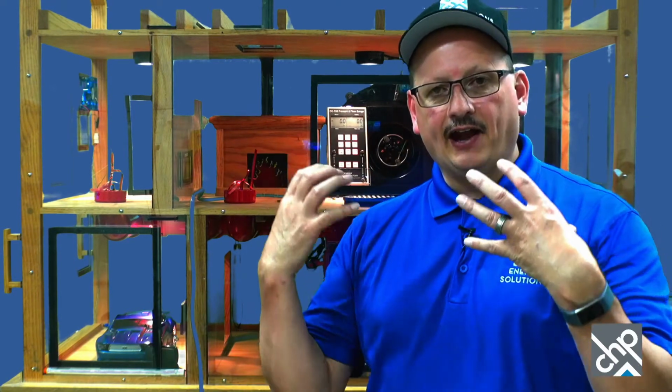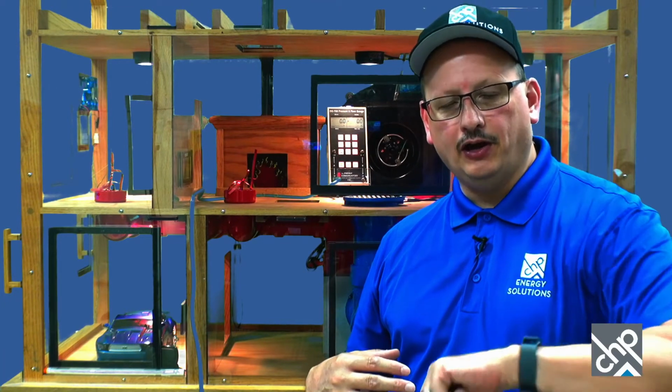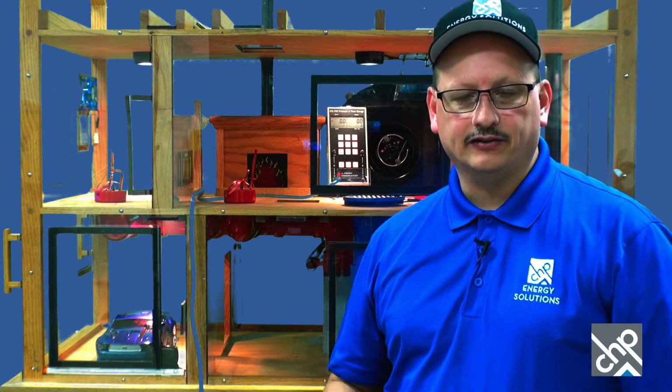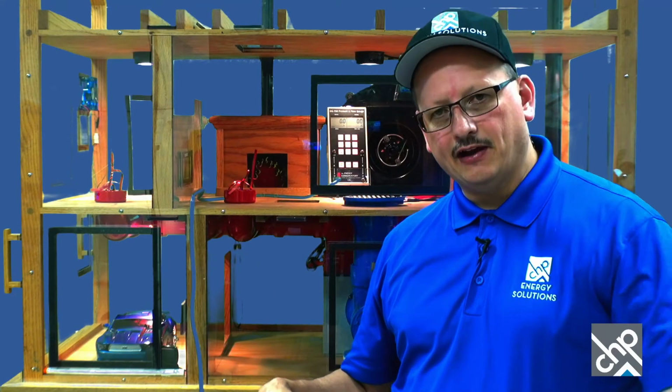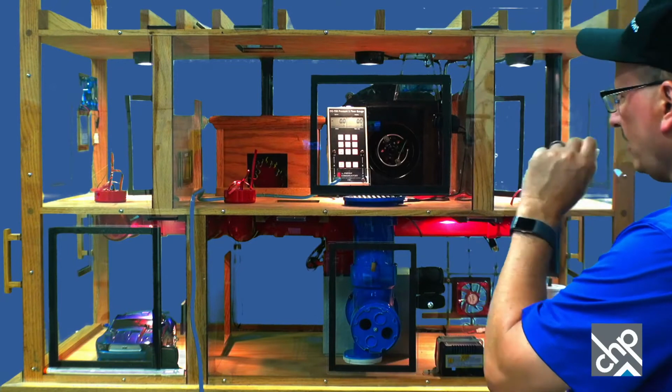When we turn on exhaust fans, it's sucking air out of the building. It's making the house go at a negative pressure, so it's a lower pressure than outdoors. High pressure goes to low. So if indoors is at a low pressure, that means outdoors is at a higher pressure, and anywhere there's holes, air is going to come in. Just like with the blower door. When you use blower doors, you get it up to 50 pascals, and when you get that pressure up, the air starts coming in those holes. And the more fans you turn on...